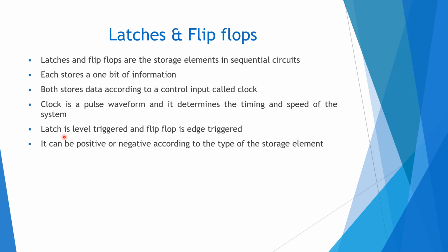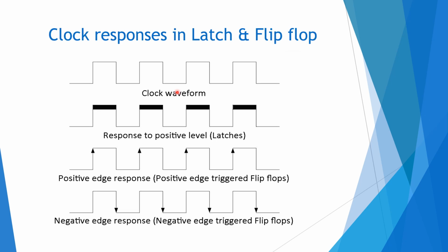So here, the difference between latches and flip-flops is that a latch is a level triggered circuit and a flip-flop is an edge triggered circuit. The level triggered and edge triggered can be positive or negative according to the type of the storage element. So these are the clock responses in latch and flip-flop. The clock waveform is just like this.